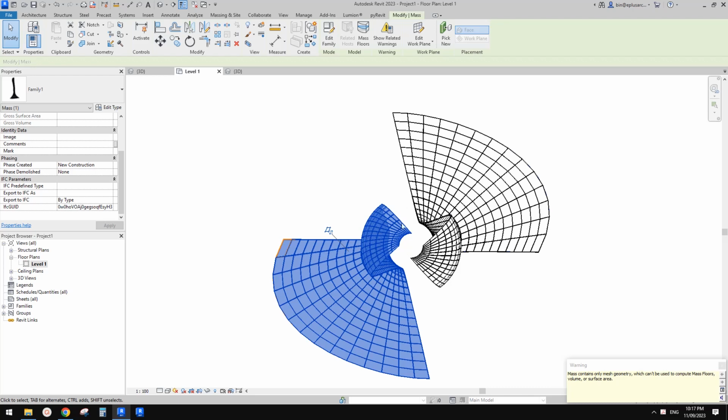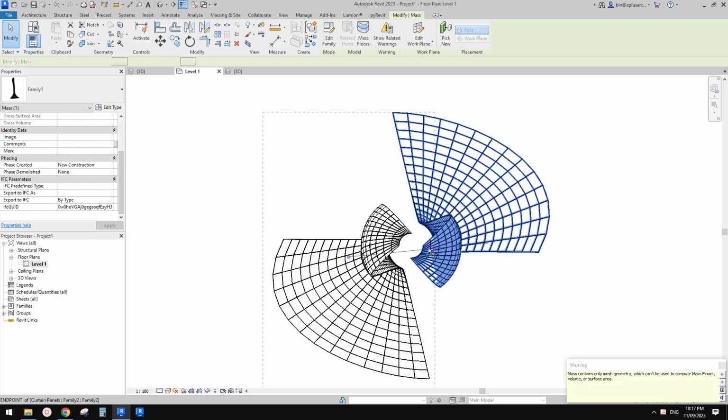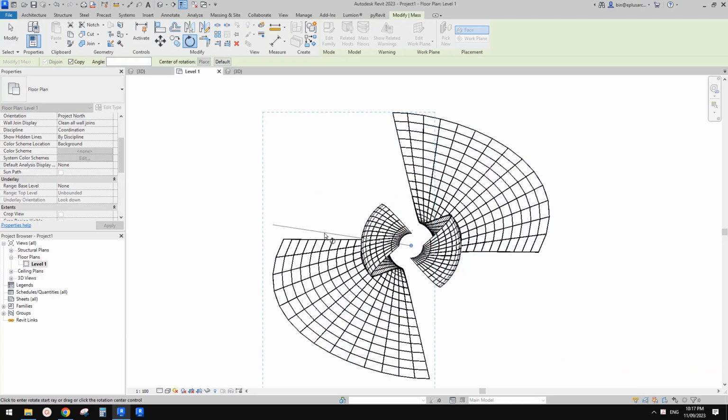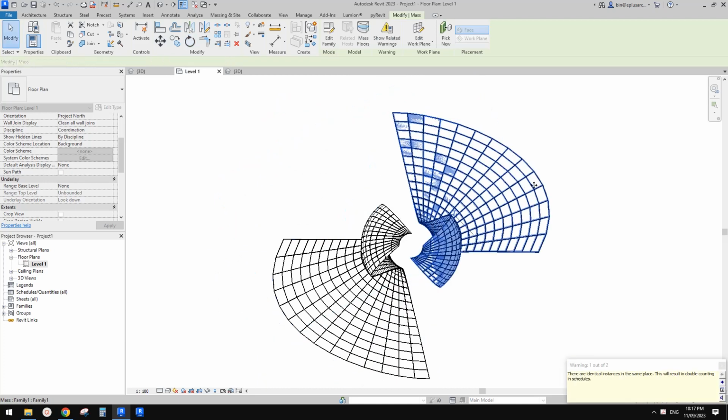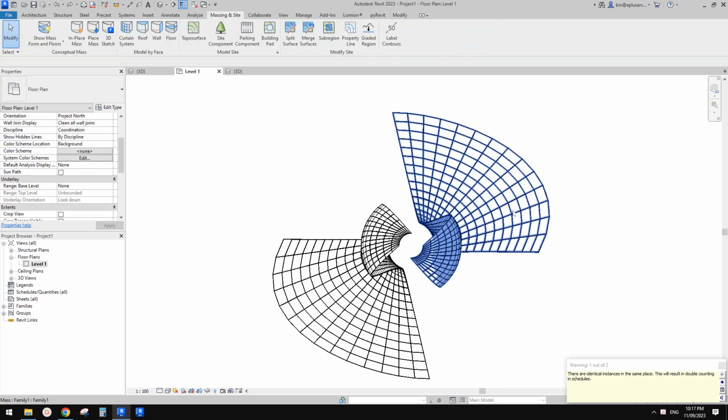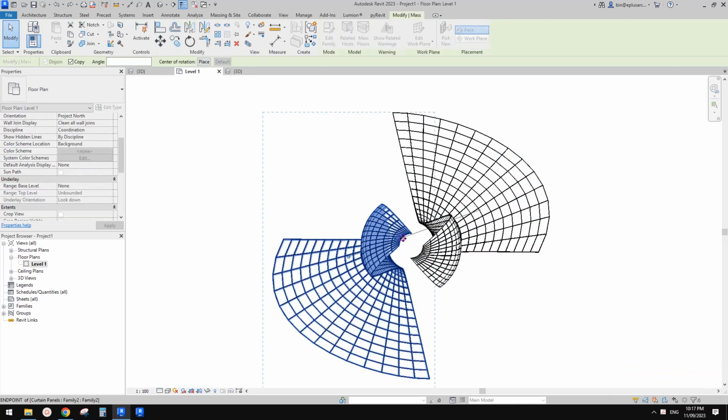Looks like this is not right, because this one should go there, not there. This is more like 180 degrees. But anyway, I'll try another one. So rotate, space, SC. Maybe I try again with 90 degrees, but it might just go here. So I'll Control Z, try again, select this one, rotate RO, space, place the center of rotation, so the shortcut is space. Okay, SC, snap center point, and click anywhere. So how about 45 degrees?